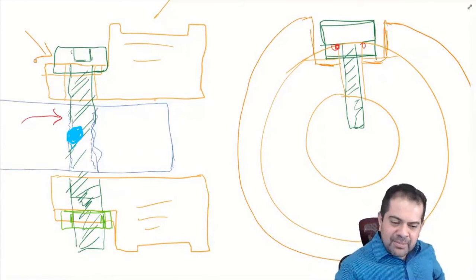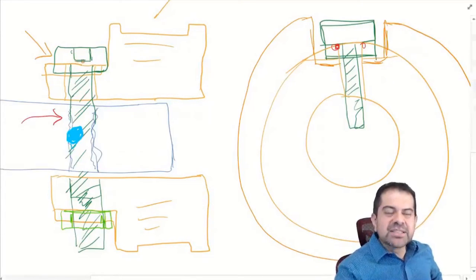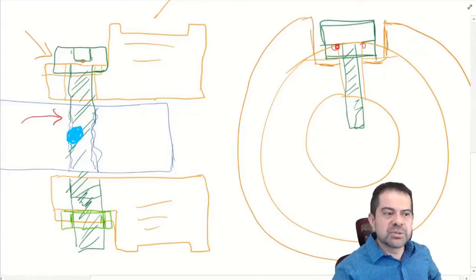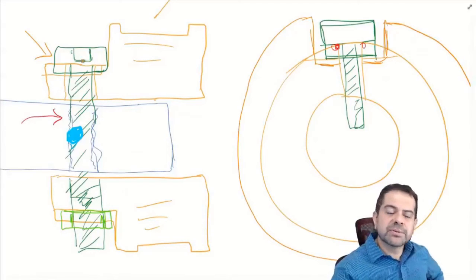I was saying, if you're dealing with a high speed of rotation, do not use this approach, because the center of mass has been thrown off. The center of gravity of that threaded fastener is not on the axis of rotation. So this thing is going to wobble. It's not going to be stable. So that's another scenario under which you would not use this approach. A high speed of rotation is not suitable.